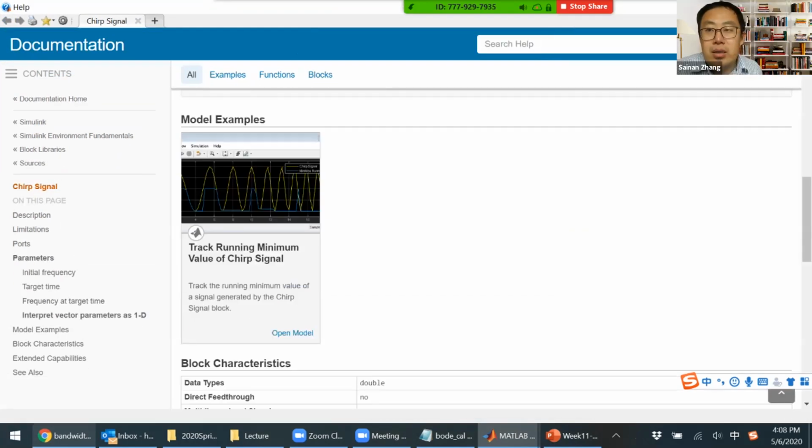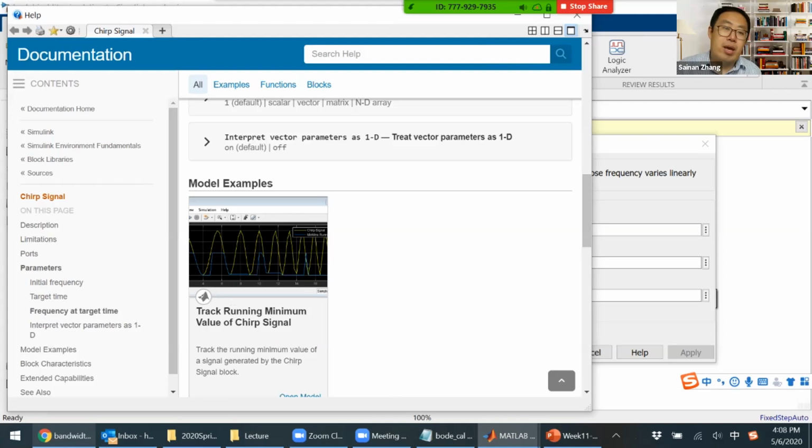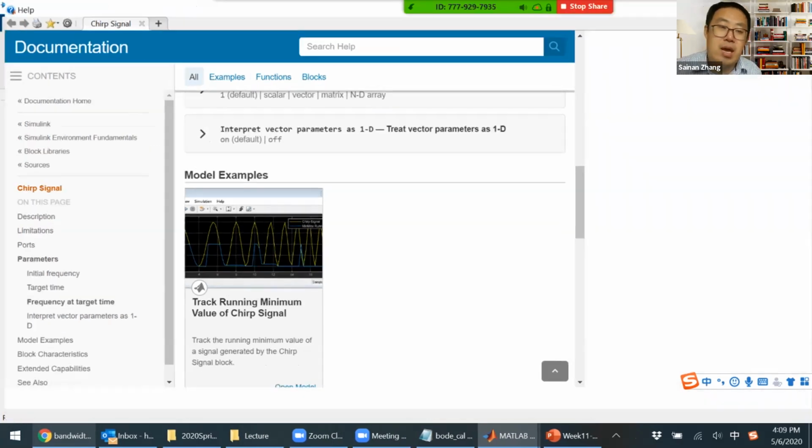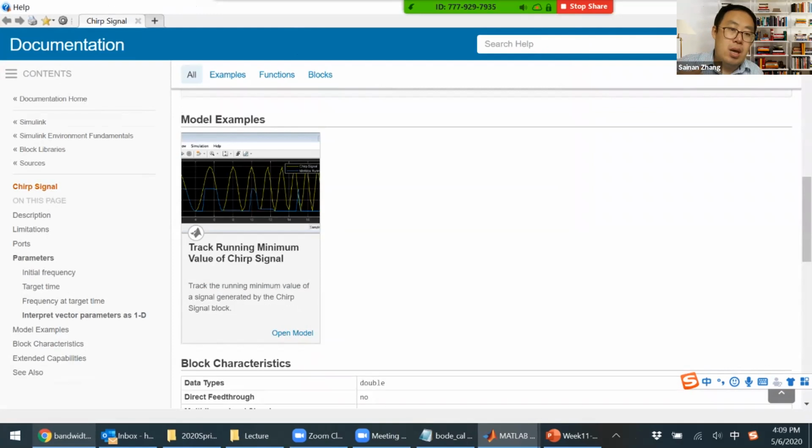I think you can put like a 30 degree back and forth for a human. Let's say in this case it is a hip, right? You can check hip angle or knee angle, whatever exoskeleton you want to simulate. For the hip, typically when people walk, it's positive and negative 30 degrees, right?